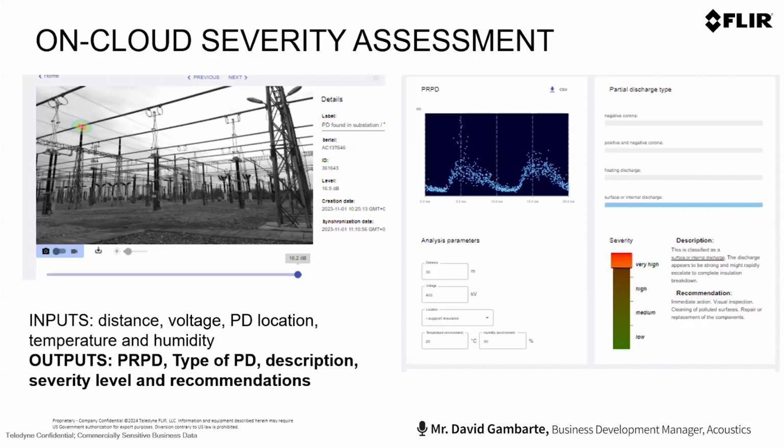I don't remember the name now, but basically with certain distances, especially long distances in partial discharge detection, if there is a low humidity level and high temperature, the sound attenuation can be quite high. So there is a certain correction factor. To be able to take that into account, we recommend to check the temperature and the humidity level in the morning or at the moment of every inspection.